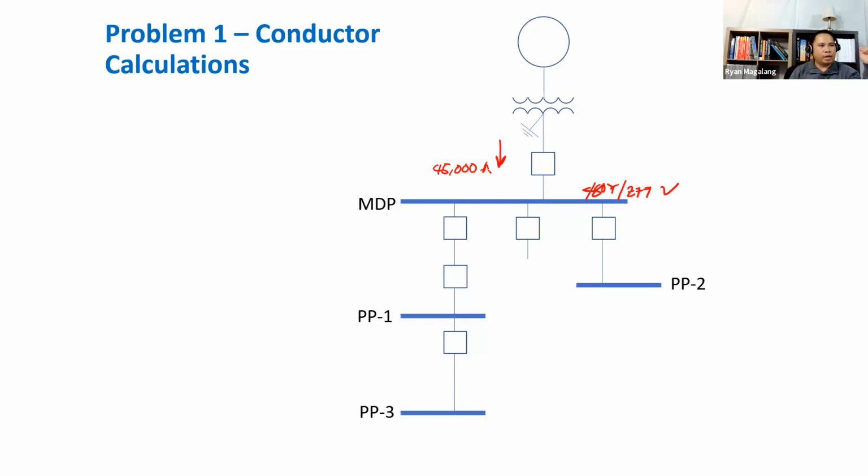Based on the National Electrical Code 110.9, we must specify a new panel with sufficient interrupting rating, and the HTP3 is being added.